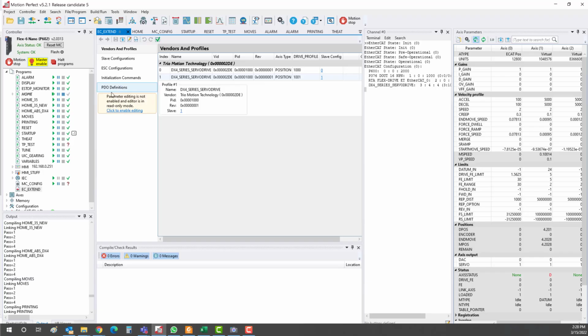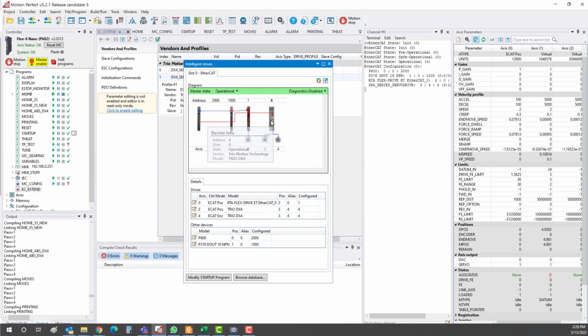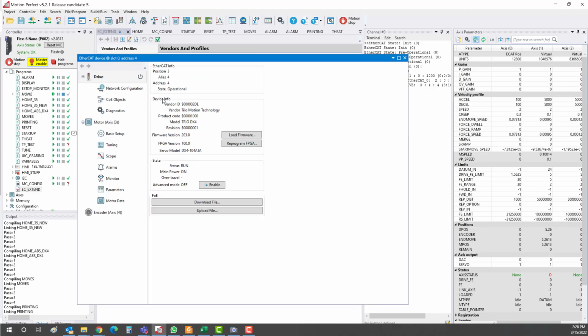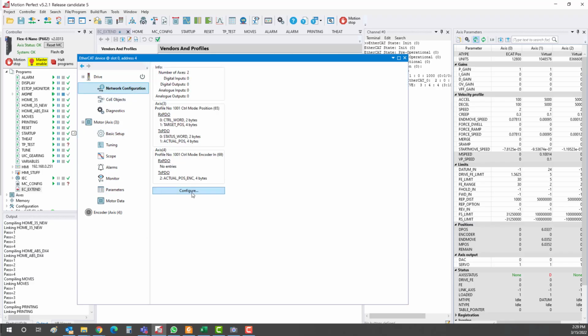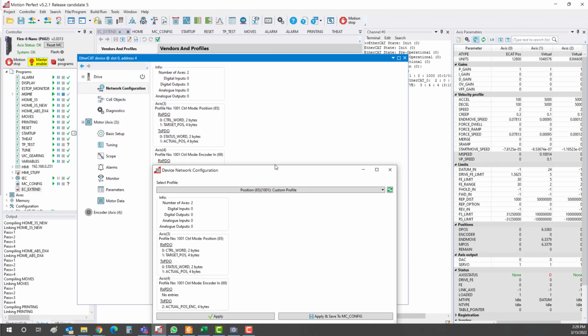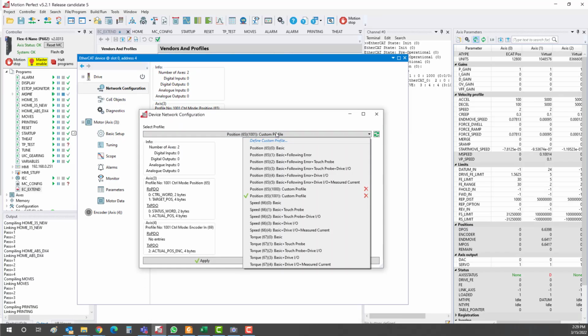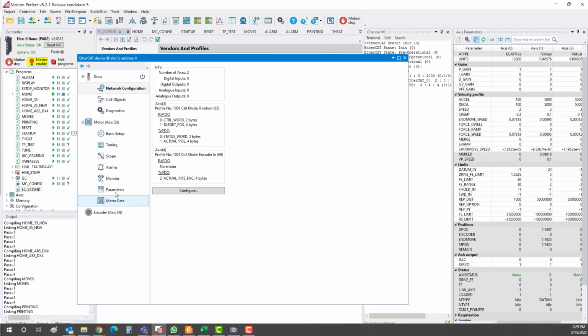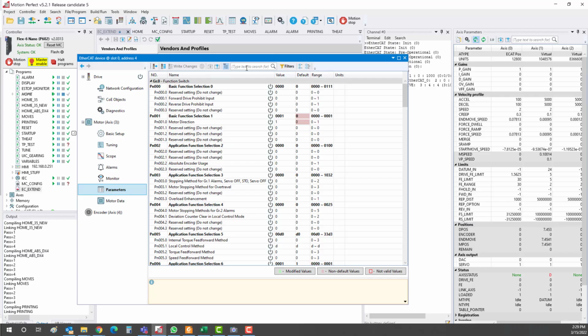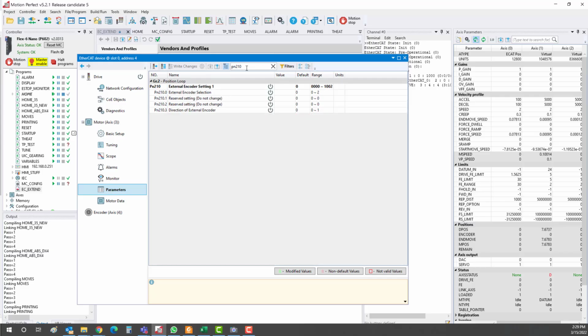That's good. And what you need as an extra step in this process is we can return to the drive menu, because for activating the second encoder we need to adjust the parameter on the drive. By the way, it will show up, I think, somewhere as a hint for us. Okay, let's get rid of this. There's a parameter called PN210. This is the external encoder setting on the drive.